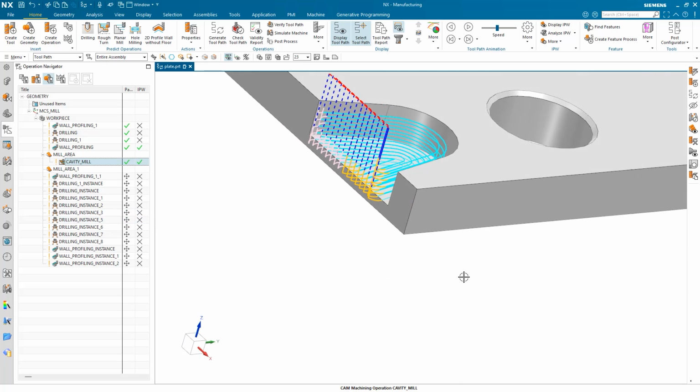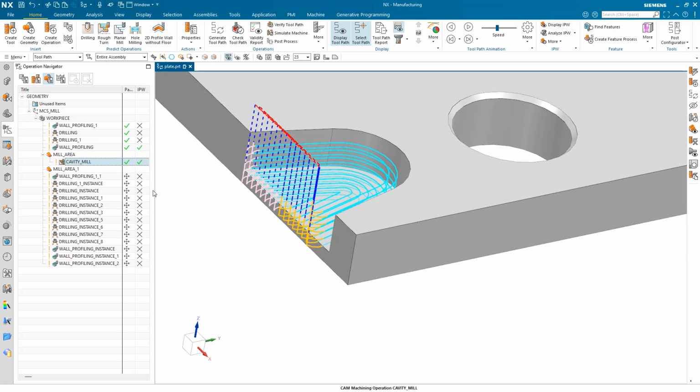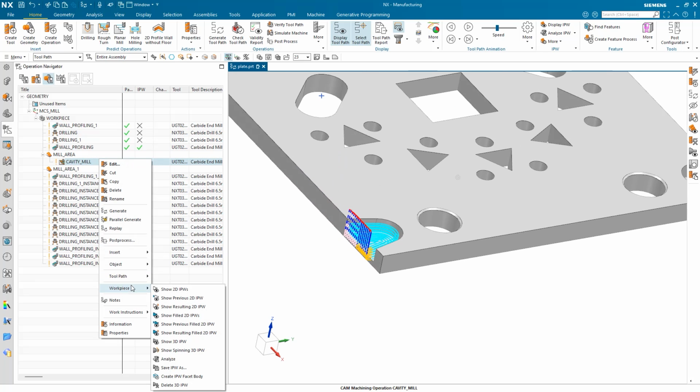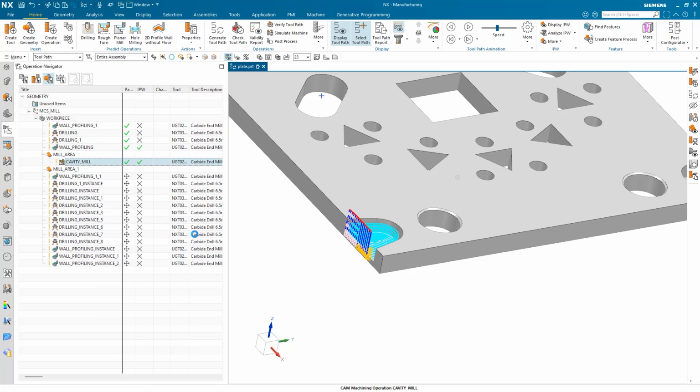I have less toolpath, right? Because there was just less stock. Now, the caution. If I'm not being super aware of the stock and all of these other little things that we know as CAM programmers can get us, and I'm just flying through this part and using transform to get the job done, I could cause a mistake.